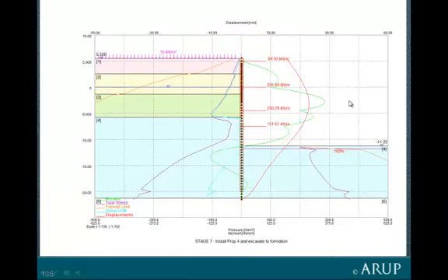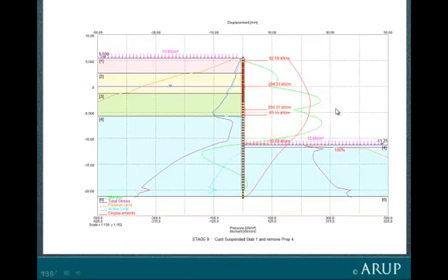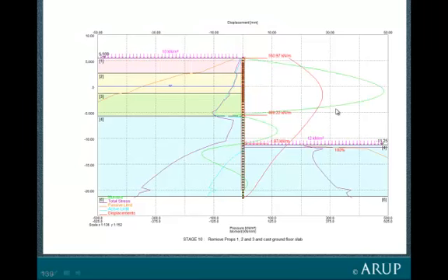We put in an extra prop. We take the excavation deeper. And then what we've looked at in this particular case is, let us suppose that as we are starting to refill, we're putting in the permanent props here, we want to take a prop out. This quite often happens, and quite often at that stage you get a computed bending moment which is much bigger. We're approaching 625 kilonewton meters per meter. Let us suppose that the sheet pile section couldn't actually take that, and we want to cut it down to something like 450.